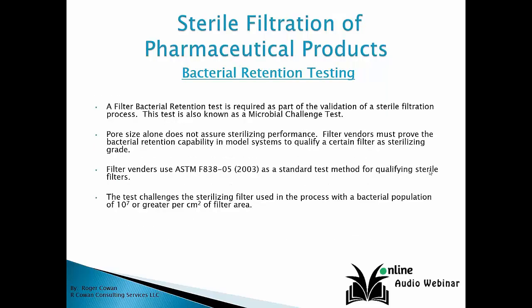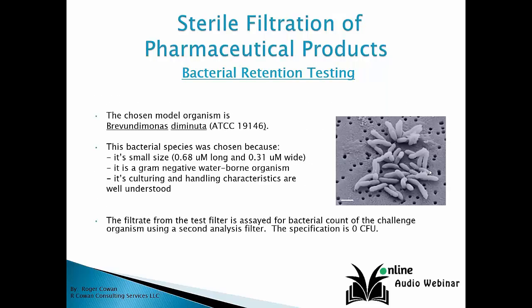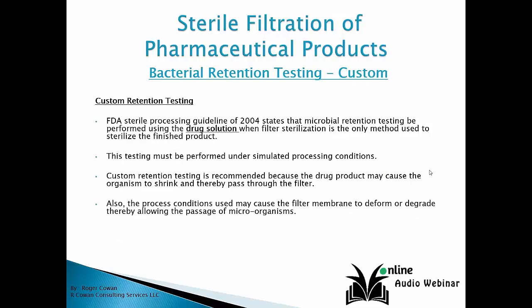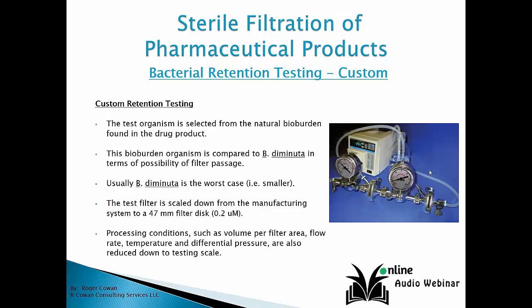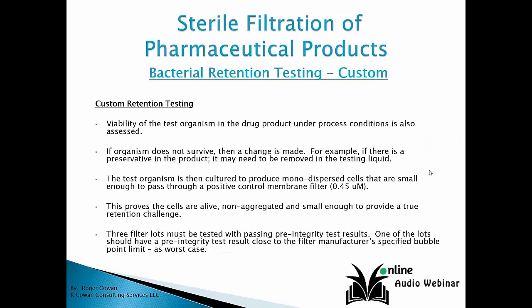How about toxicity? A thorough validation study is needed to determine if filtration of the drug product produces any toxic effect. How about bacterial retention testing? And the chosen model organism or test organism that's used. Now, bacterial retention testing is endorsed by the FDA Sterile Processing Guideline 2004. I've got pictured to the right the typical apparatus used for bacterial retention testing. The viability of the test organism in the drug product under process conditions is also assessed.